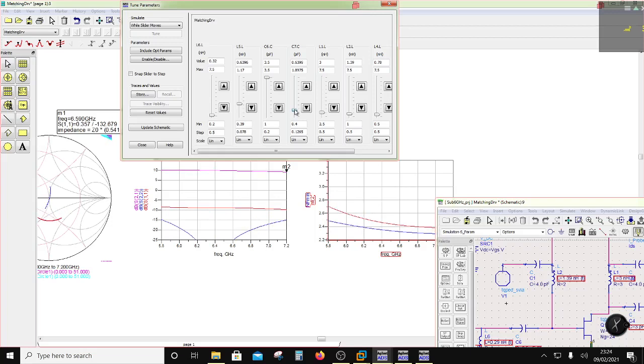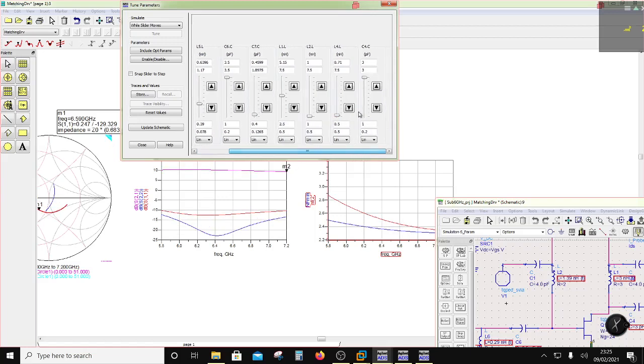So if it is mismatched, of course the noise figure will go better. That's not the way to do it. And then the third thing is the quiescent current. But then you are not tuning this as a LNA, right? This is a PA, is a different size. LNA is a different size, right? So you understand. So I have given you just the tools. Okay, I have just told you the tools. Now it's up to you to figure out what you're gonna design, right?